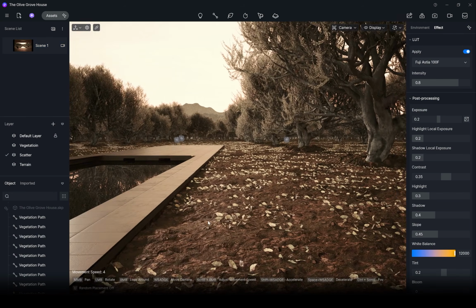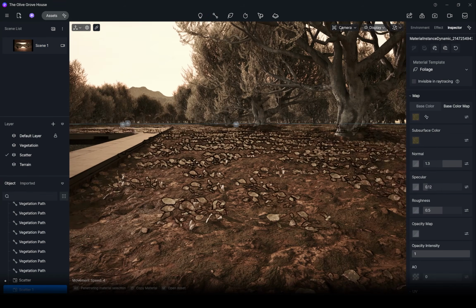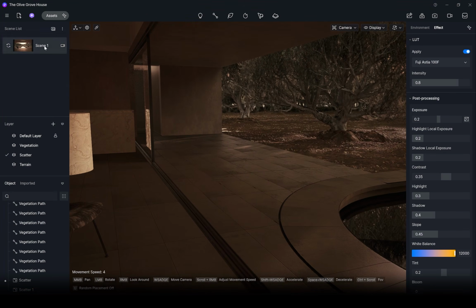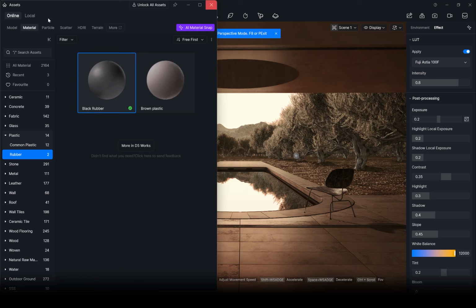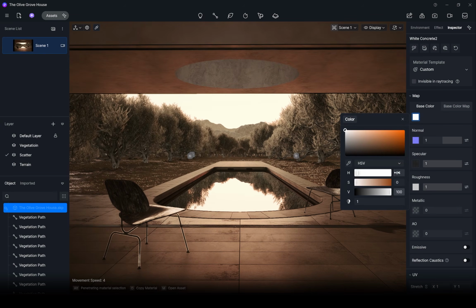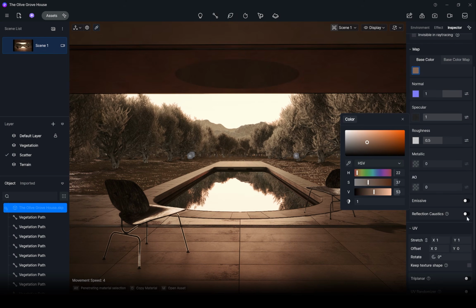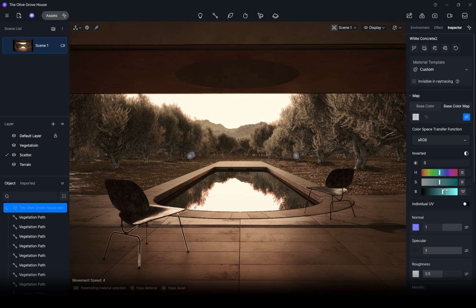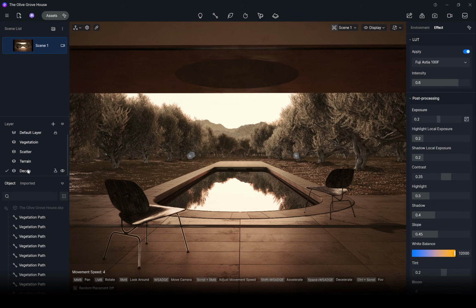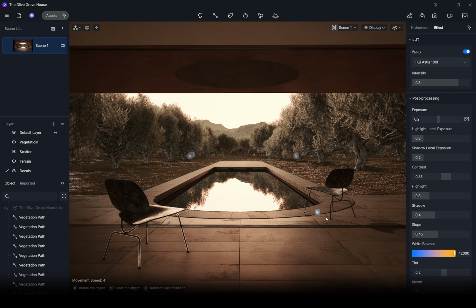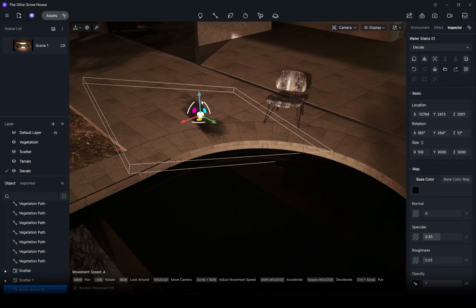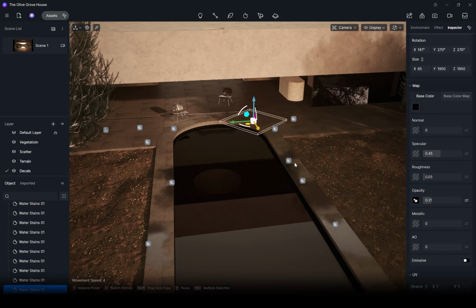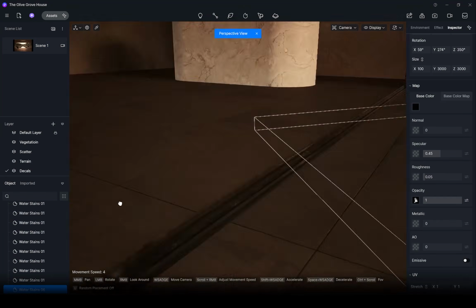With the image nearly complete, we'll add the final details. Let's copy the soil base color texture into the leaf material as well so they blend better. Then we apply a reddish concrete to the roof to catch light reflections, and copy it to the interior wall. Let's create a decals layer and add some water stains around the pool to suggest someone has been there recently. This will help a lot to build a narrative beyond just showing a static image, but creating a story behind the render.